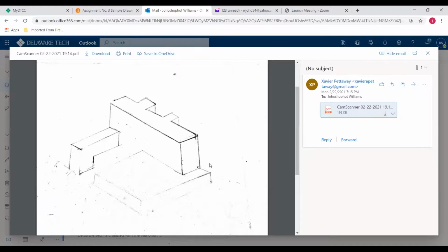You have to use the 90 degree side, the straight side, and it has to be placed against your T-square. And that might be an issue too. Are you holding that? Because it takes sometimes some getting used to in terms of using the T-square. Yeah, I just started using it again. I didn't use it before. I just pulled it out.